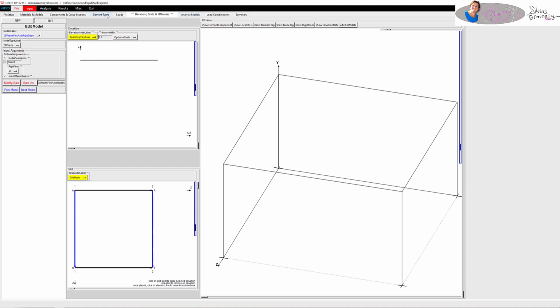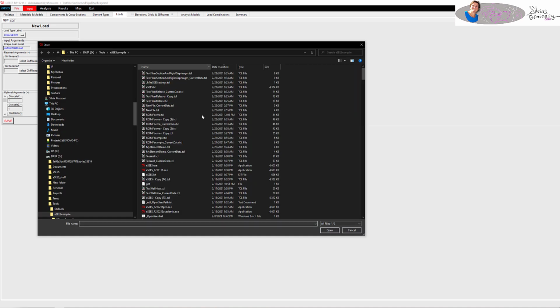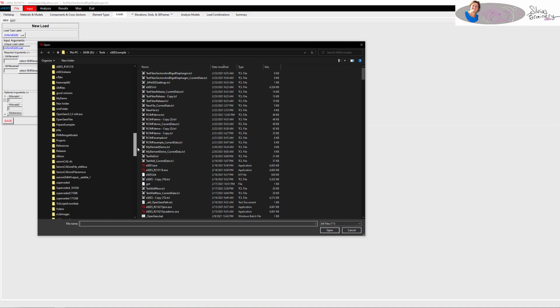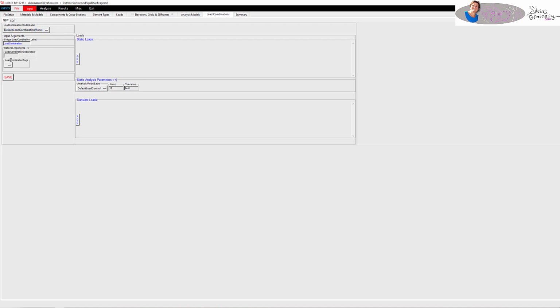It's always important to save it, and there's some glitch in here, so I want you right now to save it and maybe even rerun the saved file. Okay? So now what I'm going to do is define my earthquake loading. I'm going to subject this to earthquake. So I define a load for earthquake, and then I'm going to put that into different load combinations.